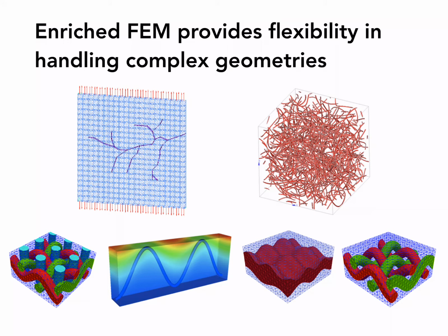Because take, for example, the microstructure from the top right, and suppose you obtain the behavior of that, let's say it's a periodic unit cell. You obtain that behavior, and then you want to see what happens if I change the configuration of all those fibers. Well, you can still use the same mesh, and you can do that, let's say, 100 times, and after 100 times you obtain an average behavior. So that is the power of these methods that you're going to learn, right? This idea of having a complete mesh independency.